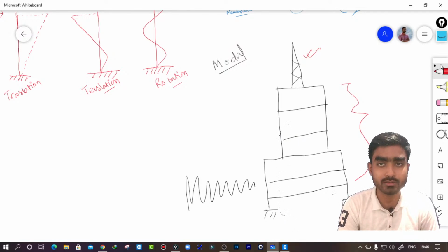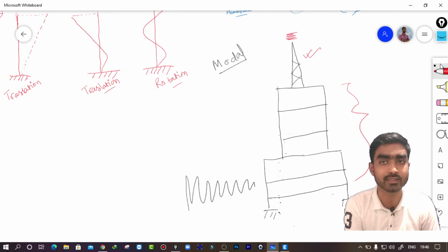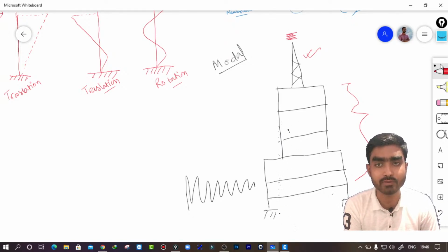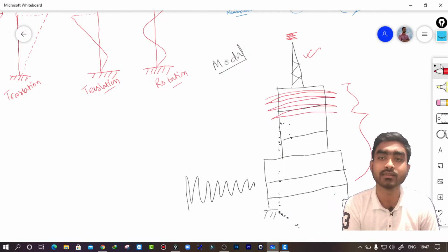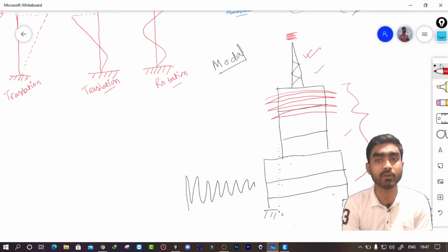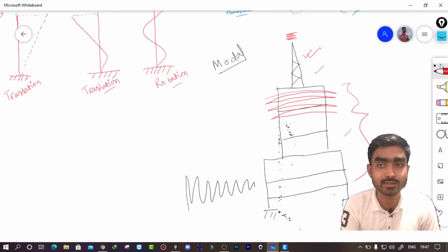Okay, because this is very small compared to the structure below. So it will move with a higher frequency like this, and the total structure will move with a higher time period, meaning low frequency, like this. Now what will happen here? The frequencies are not matching, right, at the top and the bottom. The software is not capable of understanding these two behaviors.